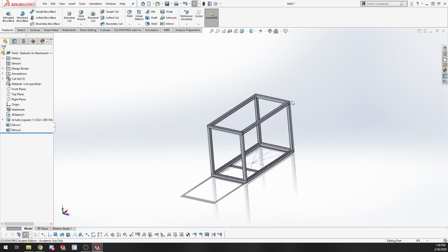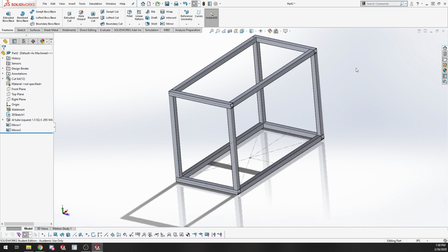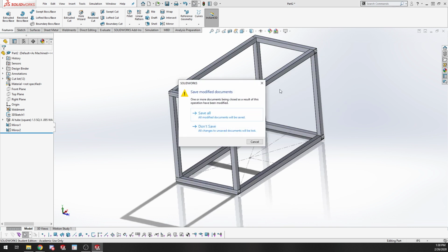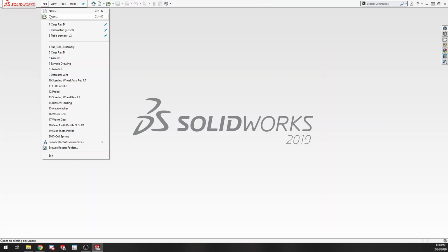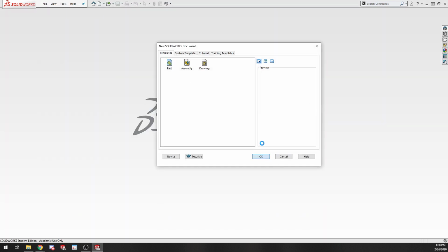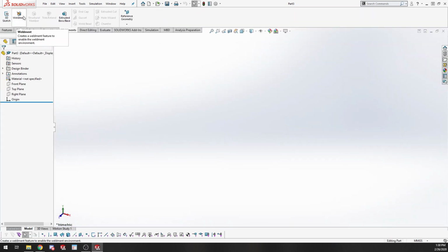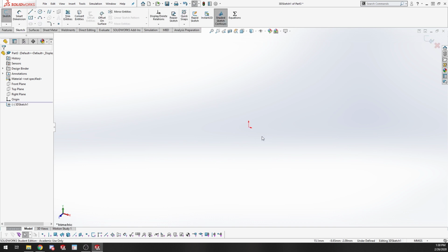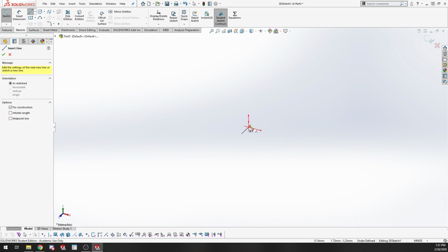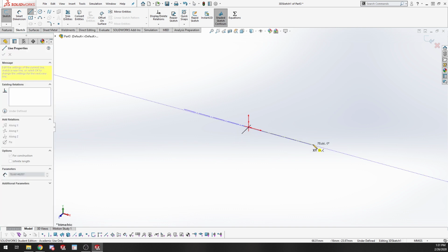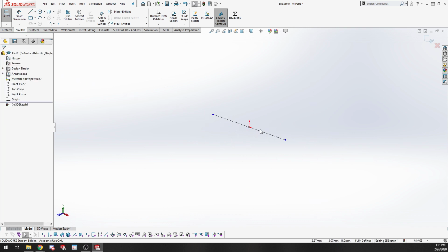Yeah, so that's a start, but of course we can go more complicated if we wanted to. I guess we can try, see how things go. So let's actually try and make a frame, or just the cockpit area. So we'll go 3D sketch, and I'll start with just a couple of center lines. Right now we're in XY, so I'll make this a midpoint center line. This is going to be my roll hoop width here. And then I will make sure that this is along X. Yep.